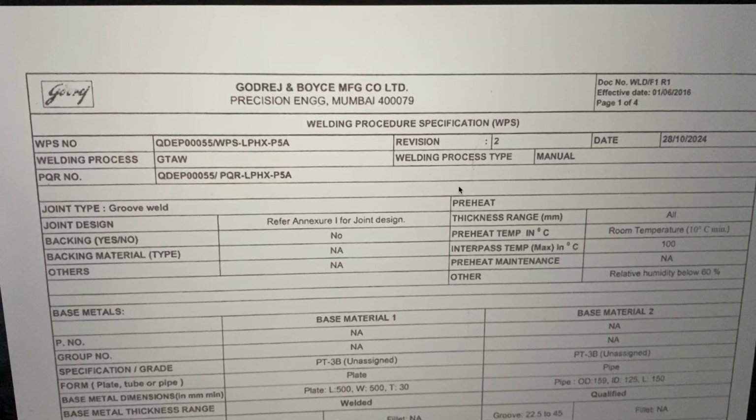That means before we start welding or during welding, half the distance between the melting point or the weld point and the room temperature shall not go beyond the interpass temperature, or we should not start welding when the earlier pass has not fully cooled down below the interpass temperature. This has an impact on the grain growth. This has an impact on the impact energy, the absorption of energy.